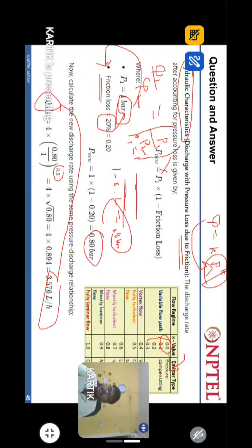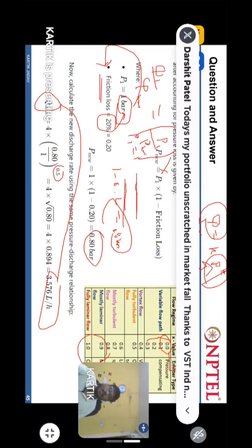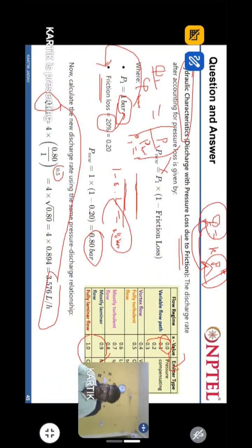So in the case of a pressure compensating emitter, we have learned that we obtain constant discharge even when we have pressure variation in our system. As the exponent value increases, the relation between Q and pressure also becomes stronger. So in the case of capillary and microtube type emitters, there is a higher correlation between pressure and discharge. As pressure varies in the system, that will directly affect the discharge.